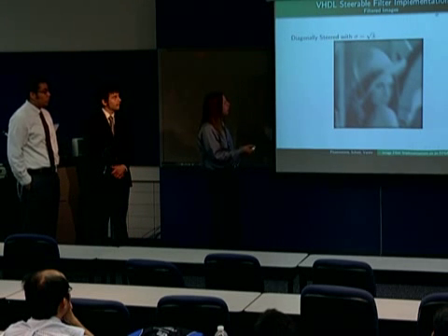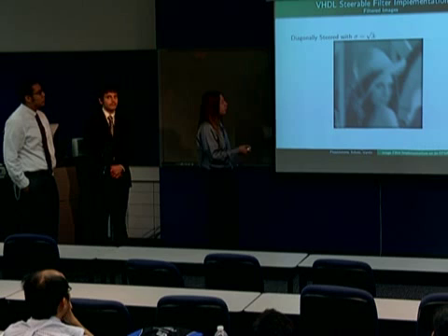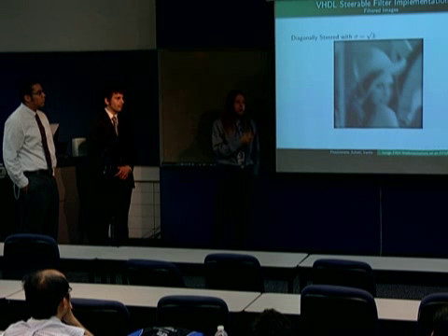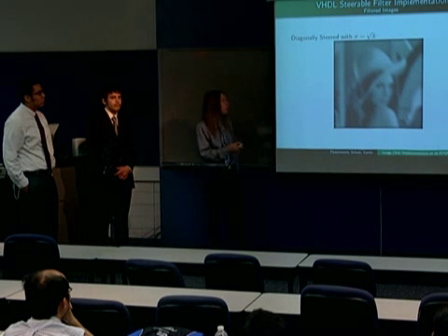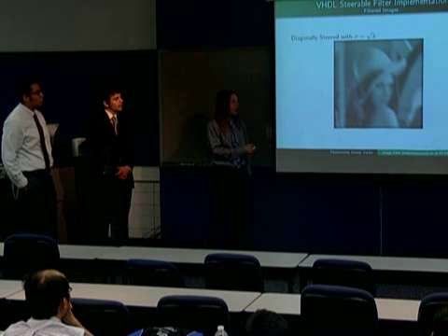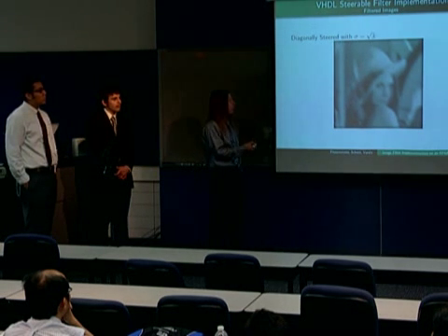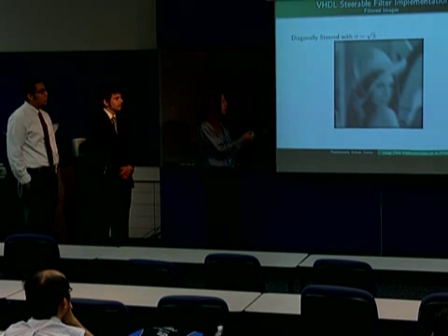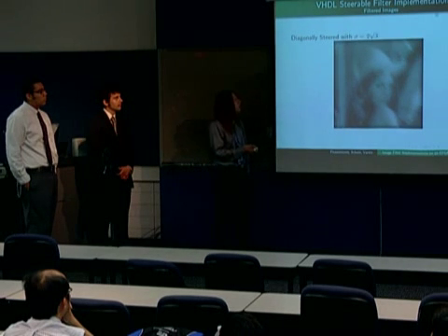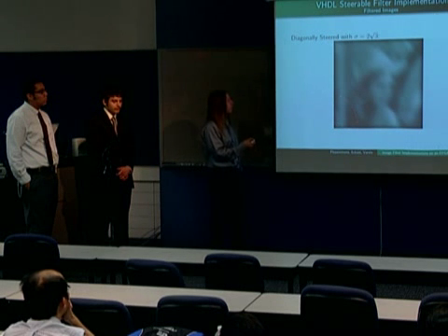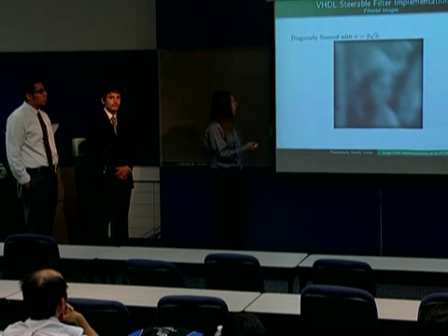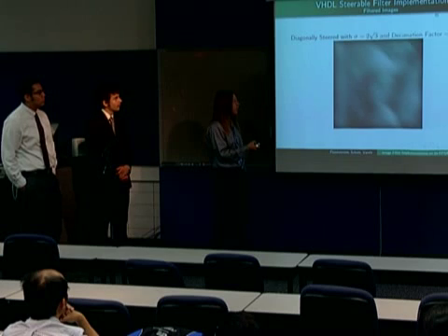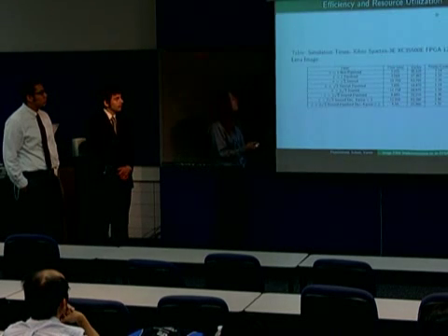And now we have the diagonal steering with a sigma of square root of 3, which is using the equation sigma y squared minus sigma x squared and taking the square root of that. So we're basically using a y filter of 2 and an x filter of 1 on the diagonal. So it's slightly more filtered in the vertical direction than the horizontal. So here's the 2 square root of 3, which as you can tell is more blurry. And finally, with a decimation factor of 2, you get a lot more significant of a blur with similar resource usages, which you'll see here.